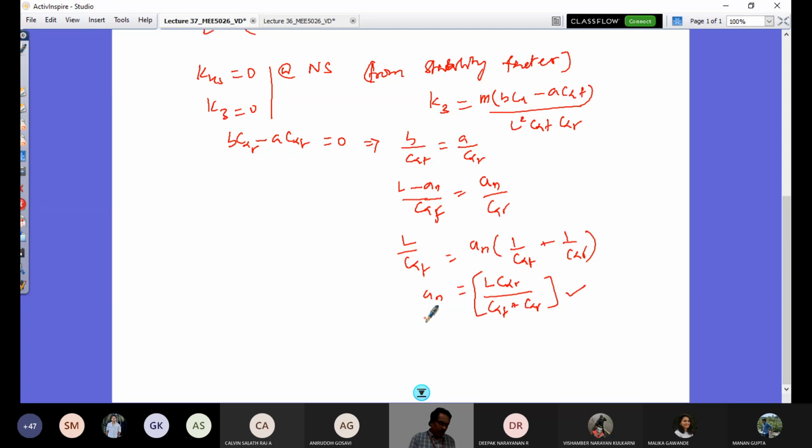So this is how you can find this. So now what is this distance E? It is AN minus A. If AN is greater than A, it is positive. If AN is less than A, it is negative, right? So this is simple understanding of static margin. When you are looking at yaw motion of your vehicle, this is an important definition which we have not talked about in our previous lecture. So I just wanted to tell this, and then we will proceed with now this suspension effect on cornering, right?